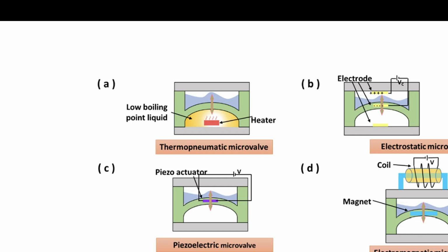This is a hydrogel microvalve, where this kind of hydrogel will be on the channels, and you have to give more pressure to pass through it. The bigger hydrogel needs more pressure, so it won't allow the fluid to go to this side. The same phenomenon can be used mechanically also, like a check valve, where an elastic structure is attached to some kind of wall. When you give more fluid pressure, it will open. With opposite pressure or less pressure, it will close.